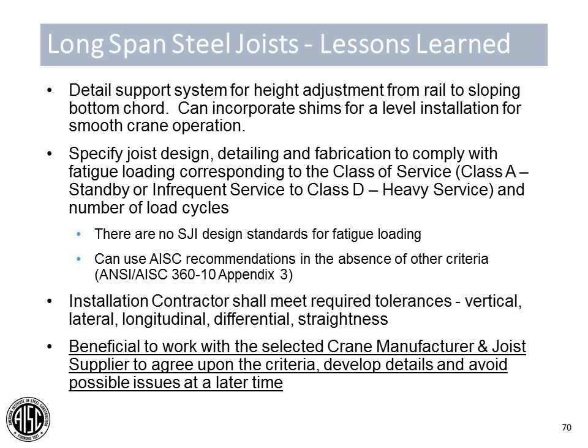So early on in the project, try to engage the joist manufacturer and joist designer and provide the AISC recommendations for fatigue criteria so that we don't run into a fatigue concern later on in the project. You may not have it with your runway, but remember, we need to be looking at these designs as a complete system, and the joists and joist girders are a part of that system.